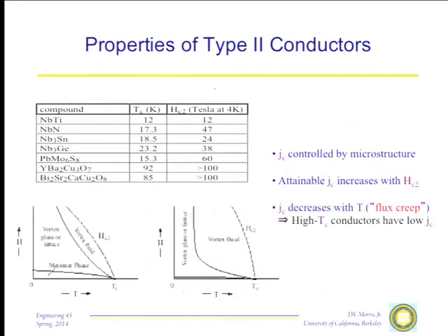And what happens with these superconductors, as you might imagine, is that as we get to a decent field and a decent temperature, and this is a typical plot for an oxide superconductor, all of a sudden you get what's called a vortex fluid. It becomes possible when you put in microstructural barriers for these flux lines to liberate themselves by thermal activation, basically the same thing that causes high temperature creep in a dislocated material, which we'll talk about later. And so they're able to move, and so you can't get the critical current up very high. And this is the battle that people have been fighting ever since 1987, and no one has really made much progress in beating it.